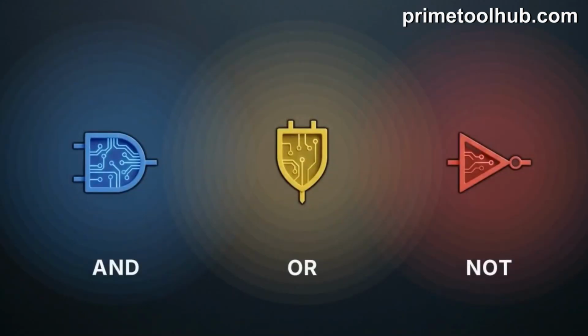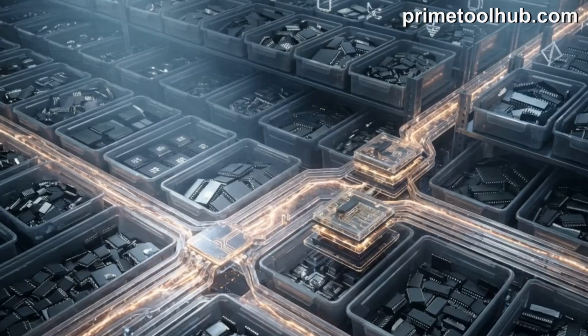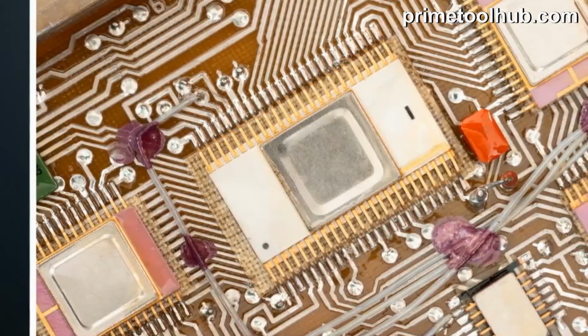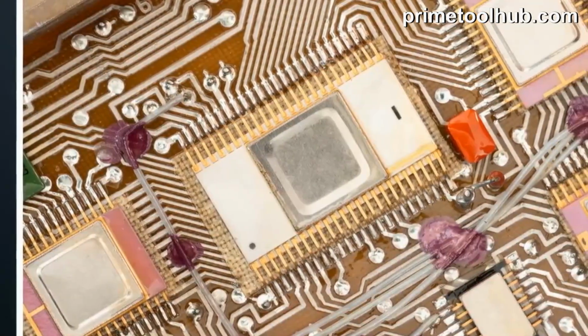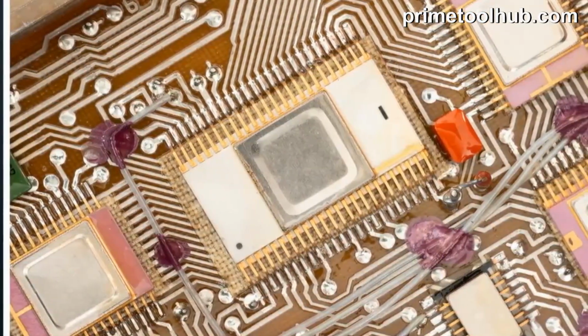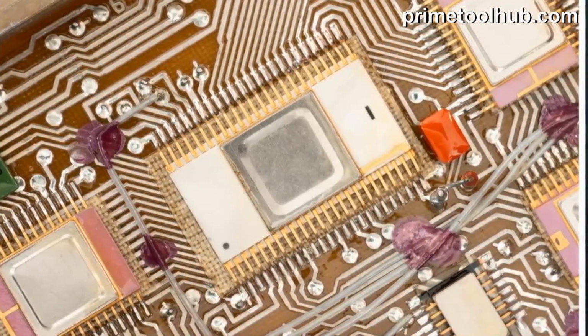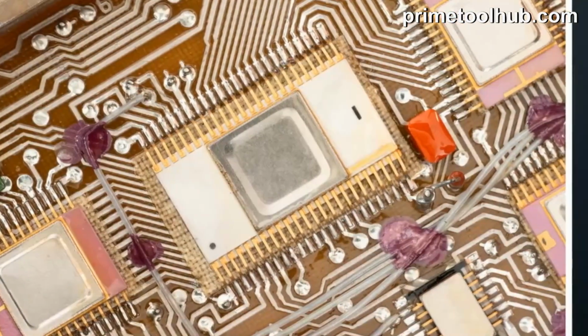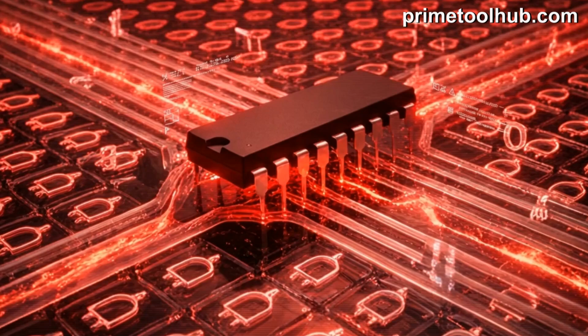Relying on a standard mix of basic AND, OR, and NOT gates forces you to purchase, stock, and wire several different types of integrated circuits for a single project. This lack of standardization severely inflates your bill of materials, the comprehensive inventory of physical components needed to manufacture your hardware. Mixing chips also draws excessive power and consumes massive amounts of physical board space.